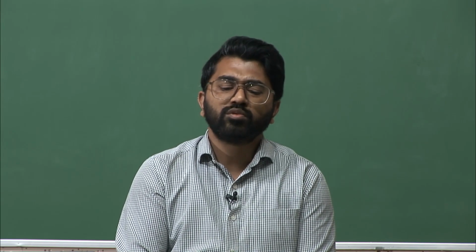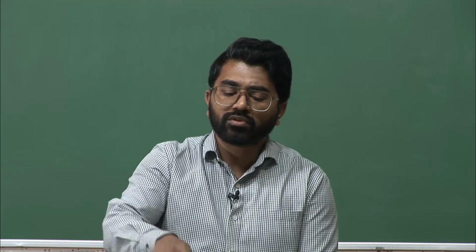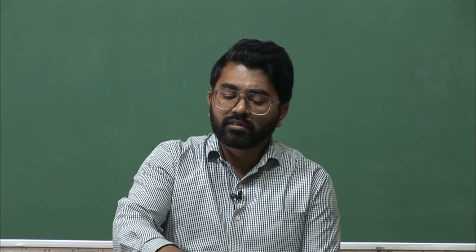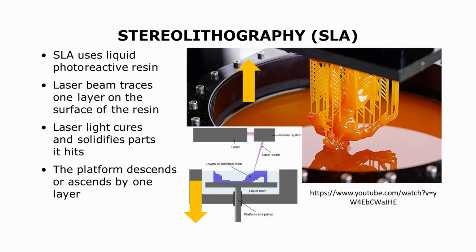Any supports are removed if there are any form of supports. Here in this figure you are looking at a bunch of supports. So, basically the model is at the very bottom, and the other ones are supports. So, these supports have to be dissolved. So, it is very time consuming, but you get a very high precision product.